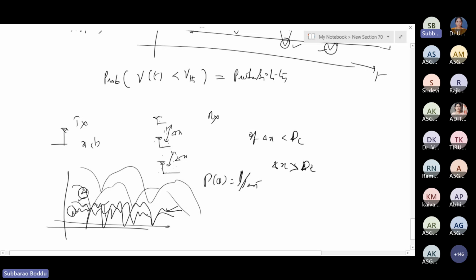By this, we get the signal out of the deep-fade duration because we are selecting the best out of many. So we get the signal out of the deep-fade conditions when compared to the single antenna. So this is the motivation to go for diversity.